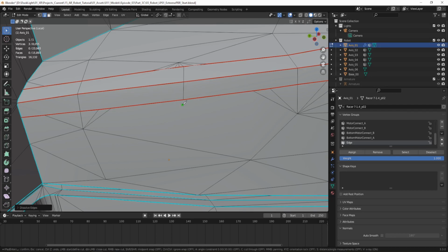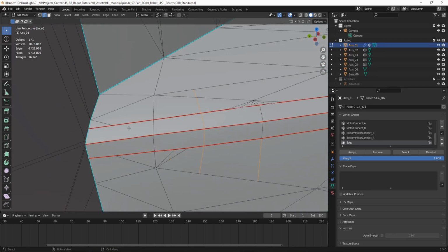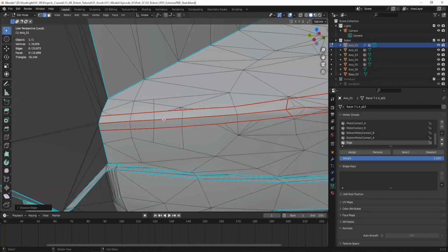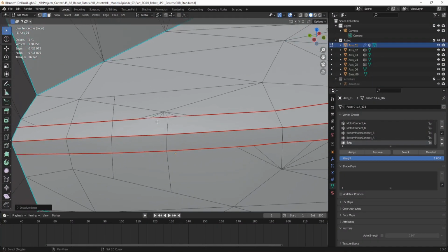And what we can do is we can take the knife tool and we can just make it cut. So that's a straight cut. We can even make one here. So straight down, pressing the A will give it a straight cut. And there we got some more quads here. And if I select these, I am basically making a whole new topology.